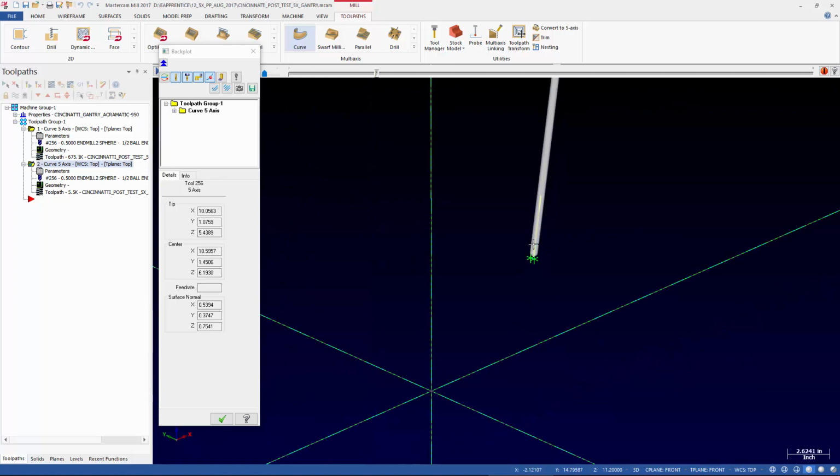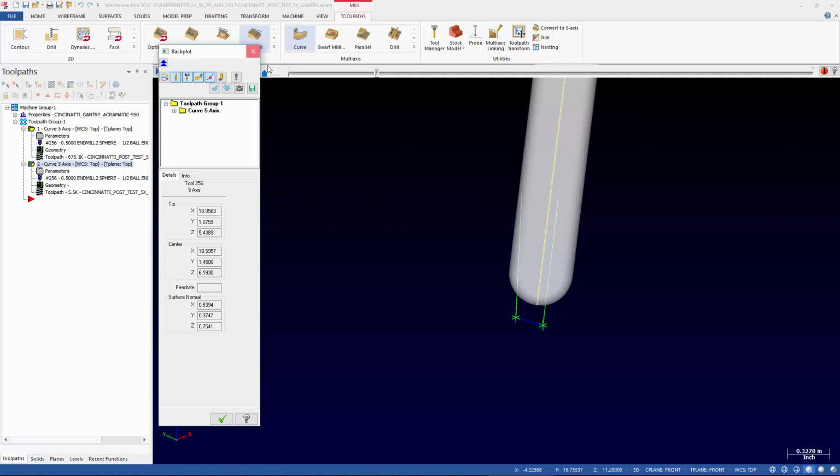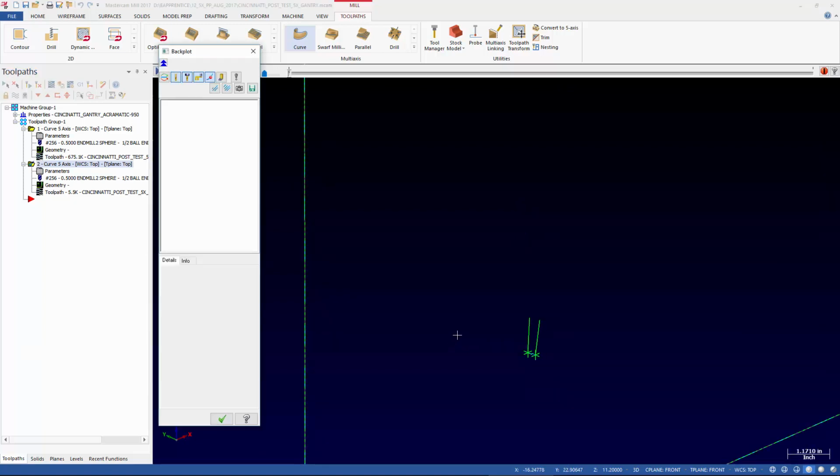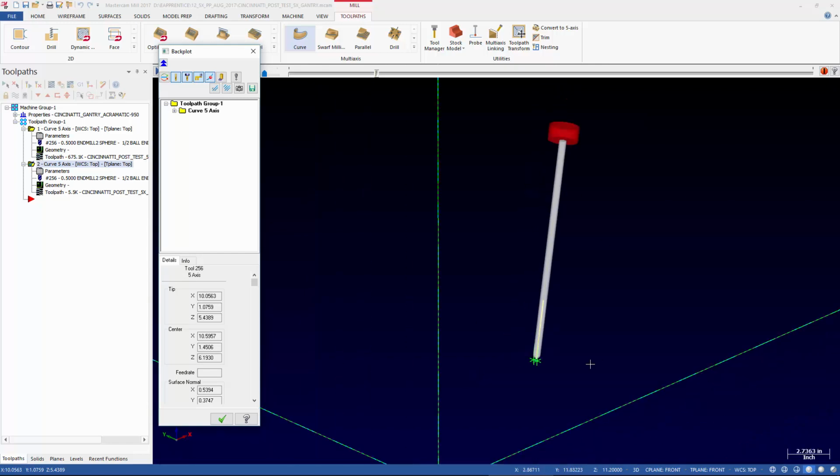our tooltip, you can see I've got a little bit of angle between these two lines here. Down here, it looks like a relatively small motion. The problem is when we visualize it with the actual long tool, you can see here's the back end of the tool at this point, and then by the time we swing over to this other vector, we've moved like 3 or 4 inches up here. We've only moved maybe a 1/4 inch down here.